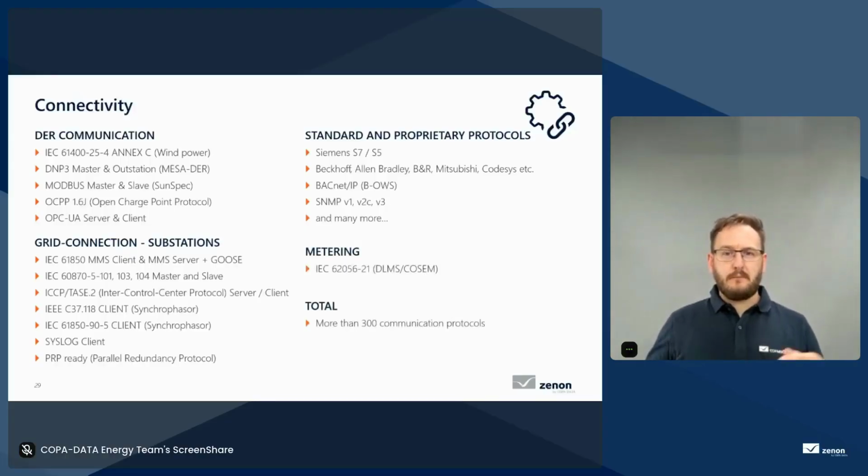And let's not forget the ability to monitor production, exported, generated energy requires metering or an energy meter of some sort. And here we can specifically focus on the majority, DLMS or COSEM, IEC 62056, to communicate with our meters.